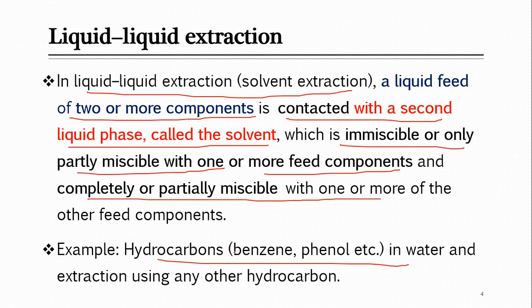definitely these hydrocarbons will have more affinity towards the newly introduced hydrocarbon. So they will be transferred to it, they will be miscible with it, while the water will not be completely miscible, or will be partially immiscible. We should select such a solvent which has no affinity for this component. Here we have water, so in that case water will not be transferred, the hydrocarbons will be transferred towards that liquid and they will get separated.